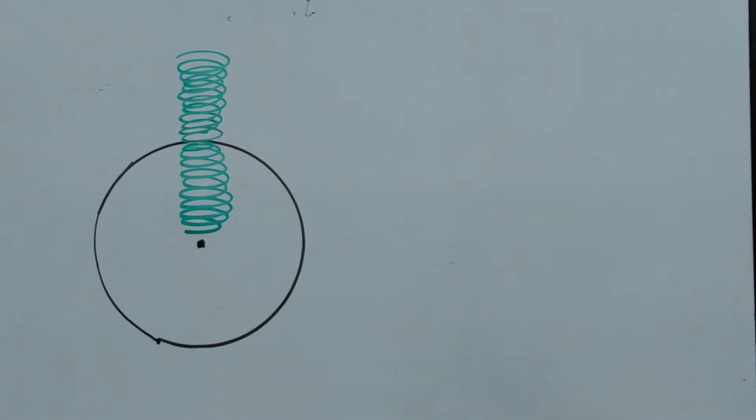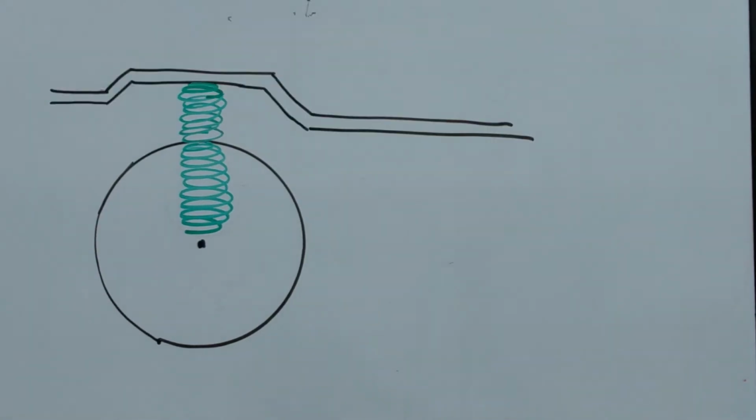In a coil spring suspension system, we need at least 3 links of contact in order to provide stability for the axle or to provide stability for the suspension. Some other links in a suspension may be called control arms or radius arms. Radius always implies that they pivot on one end and swing on the opposite end.